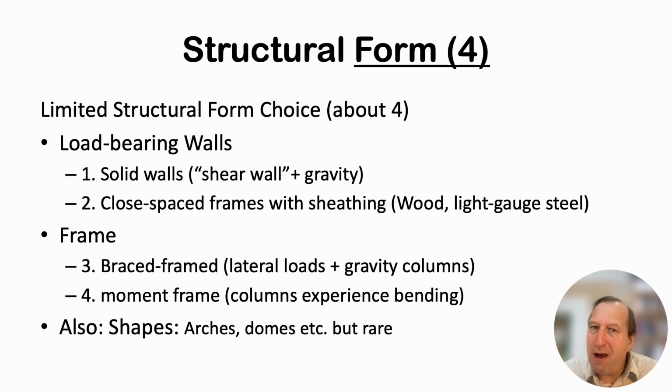And again, there's not as many choices at a big level of how we form our materials to form a structural system. The one obvious one is to make it out of walls and floor slabs. You know, you can do solid floors, solid walls, put them together, you have a structural system. Now, by solid walls, we're often dealing with what we would describe in the profession as shear walls, because they're really good at taking lateral loads in shear down to ground.